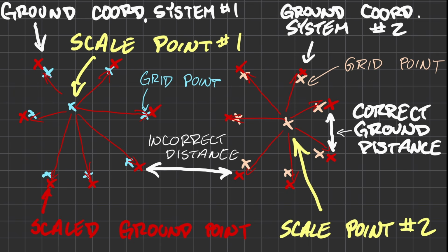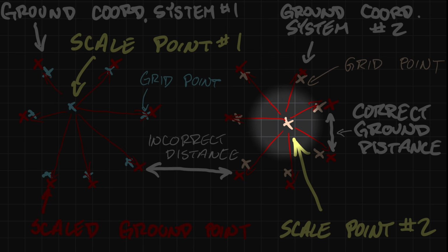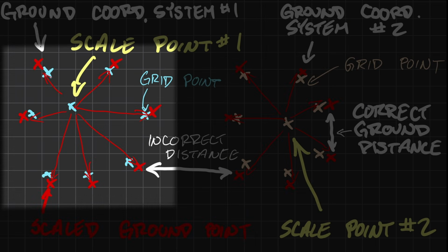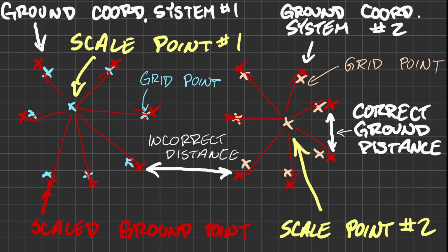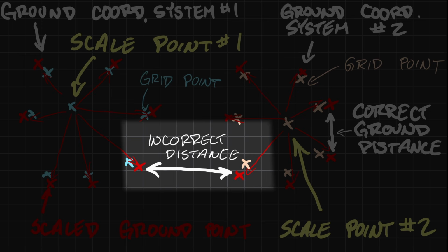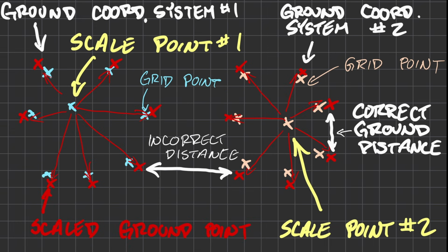If you have a project with 2 or more scale factors being applied, you're essentially creating 2 or more separate and distinct coordinate systems. You would not want to set up on the edge of one and backsight a point in the next coordinate system over. They are not going to be scaled about the same 2 points and won't agree with each other properly. 99.99% of the time, using multiple scale factors is not needed and is more trouble than it's worth. But this starts to explain one reason why we can't have a single statewide ground coordinate system.